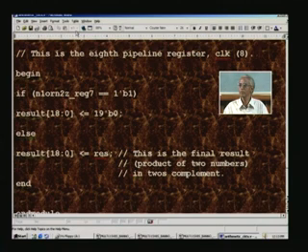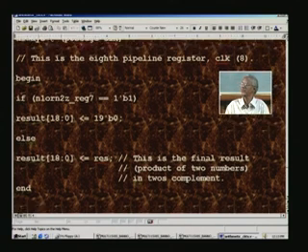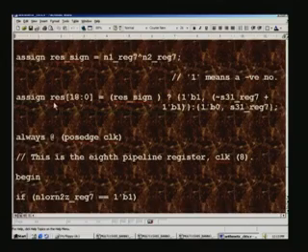So that has also propagated, and based upon that, if it is 1, naturally the result is 0. So we force the result to 0 by this statement, otherwise, in the else statement, we assign the same result which we had just now computed using that assign statement RES here.